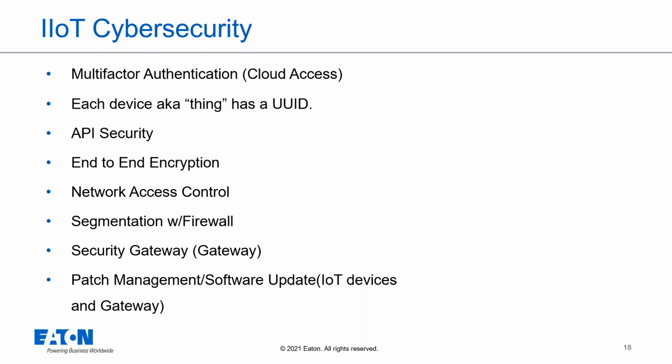I remember back in the day when I was working with serial communications, you could run a discovery and say, I'd like to discover an active piece of equipment, and I'd like to look between Modbus address 1 and 10, and then it would just keep pinging those addresses and tell you if there's a device associated with that particular address.